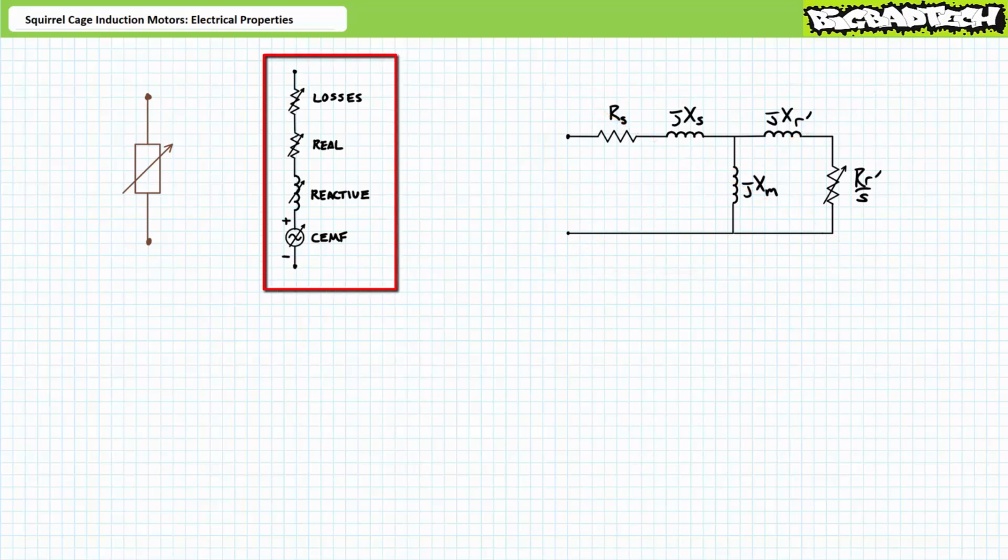In the interest of balancing completeness with timeliness, we're opting for the not so easy method, where each winding is visualized as different impedance components in series with a variable voltage source in opposition to applied voltage. This does require a little bit more involved circuit analysis than the easy method, but it yields a reasonably complete picture in a reasonable amount of time. Do not for a moment think this is an officially sanctioned model accurate in every respect, nor does it represent reality in every detail in every sense.